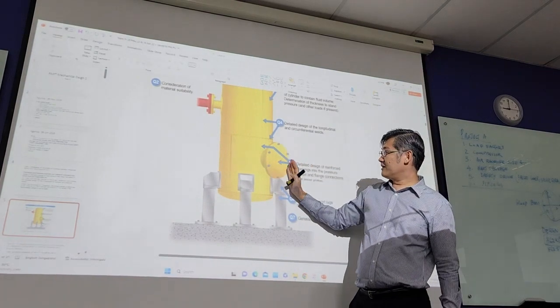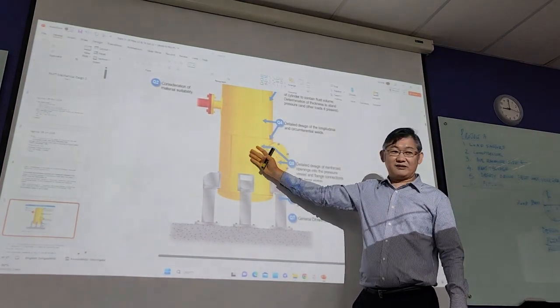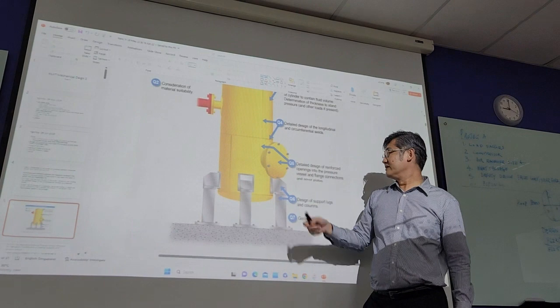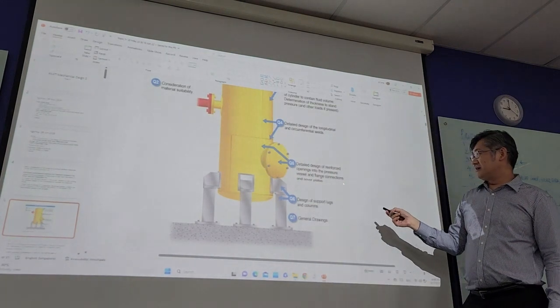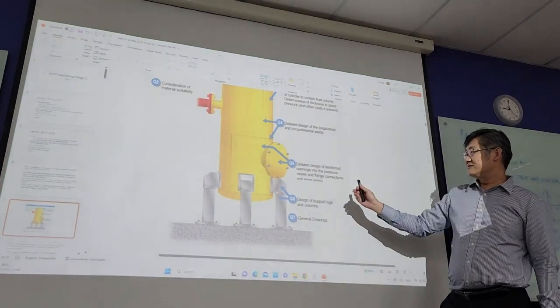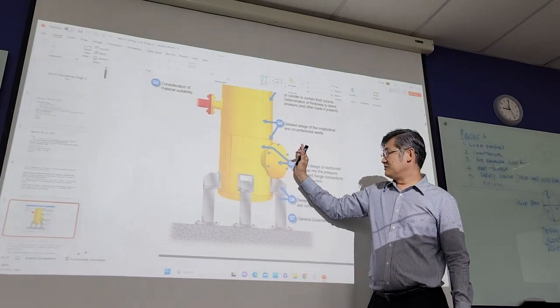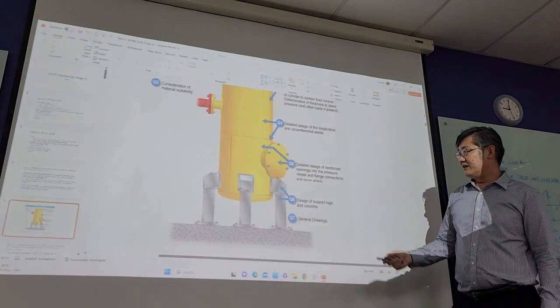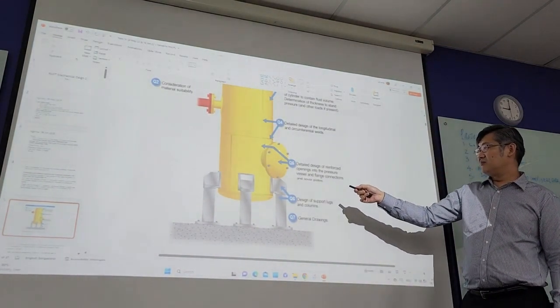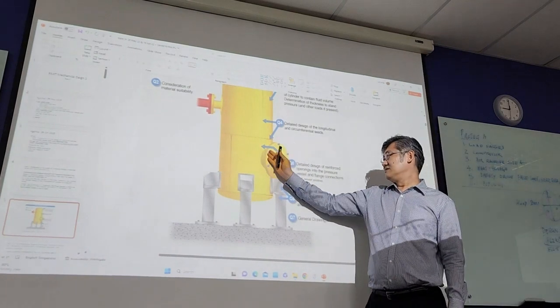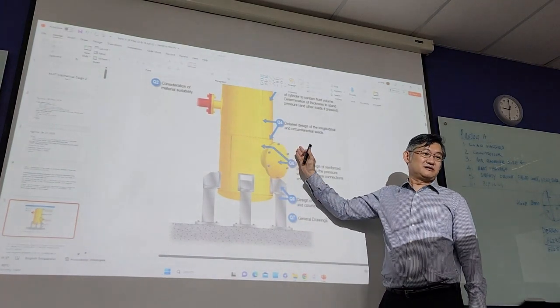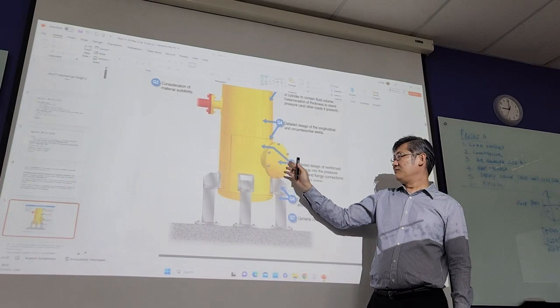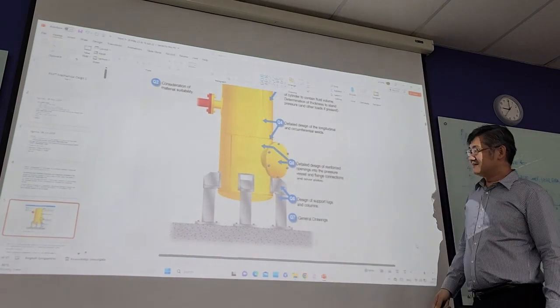So all these flanges have to be able to prevent air from coming out. So flange connection and cover plate. Cover plate to cover the flange, and then the bolts, we have to calculate the force distribution. How many bolts we need for these purposes.